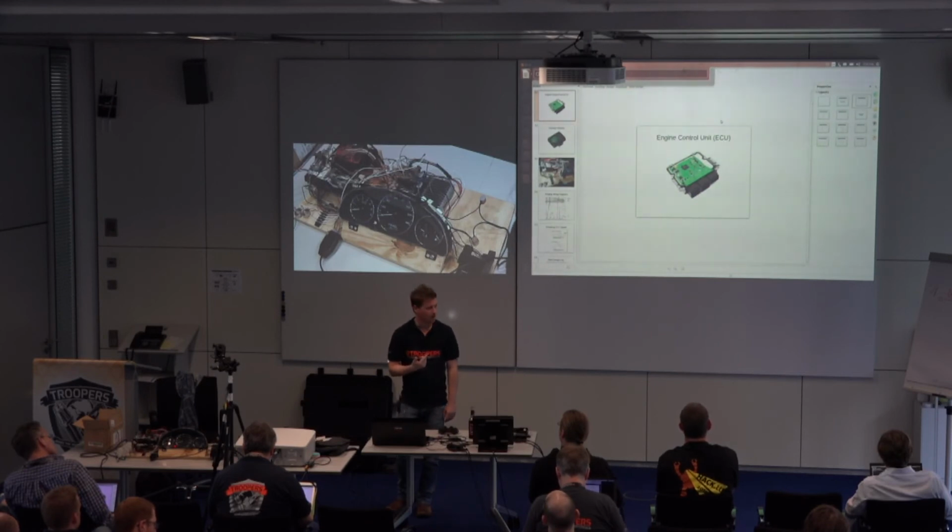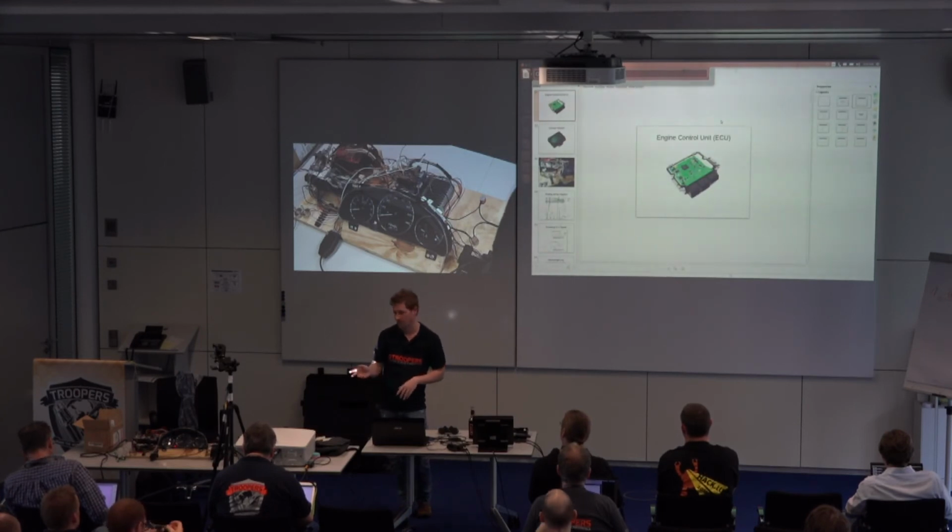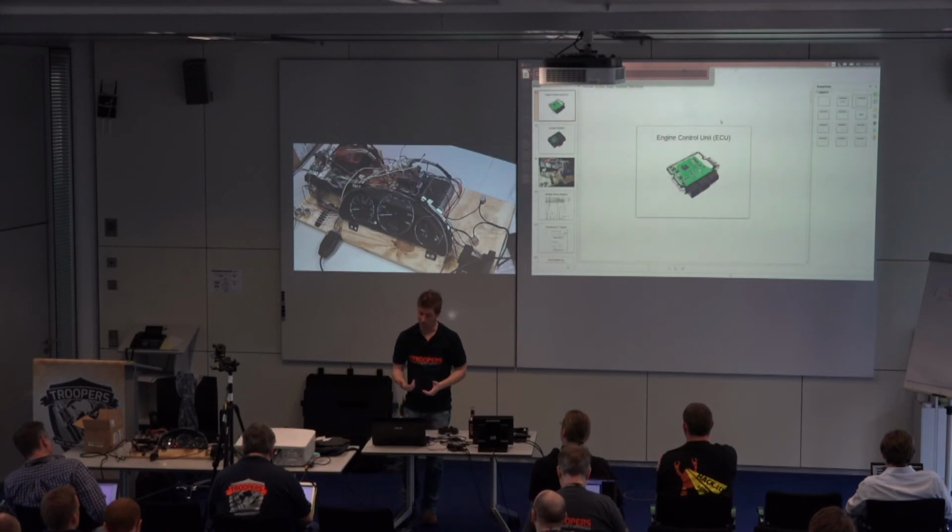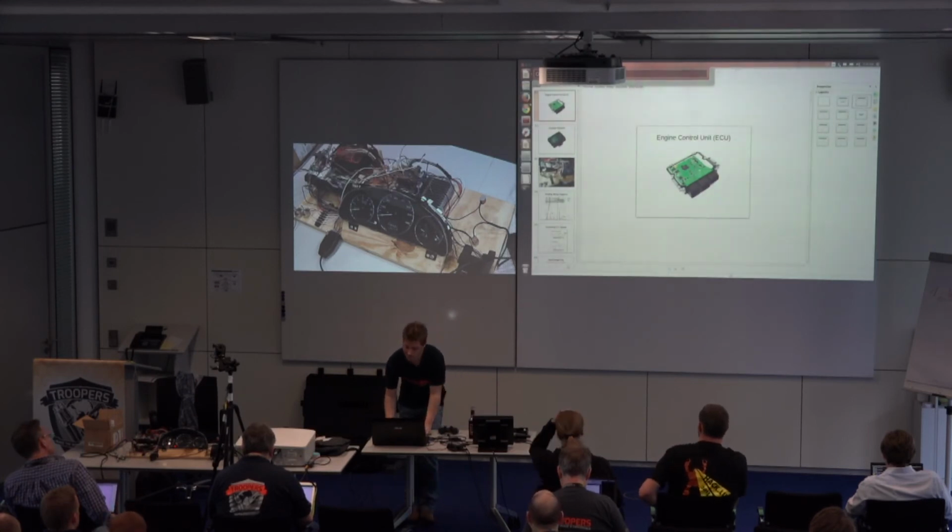One method to do it on a real car to eliminate some of that noise is to pull fuses for some of the devices you don't care about. Just look at what fuses control what, and disconnect them from your car. That'll eliminate some of the noise. It's a similar setup as a test bench, but a test bench can go really, really quick. If there's certain signals you want to know, you can basically just look at the wiring diagram for what wire it is, simulate that signal, and check the CAN. And then you'll have it, and it'll work on a full-blown car. It takes very little amount of time.